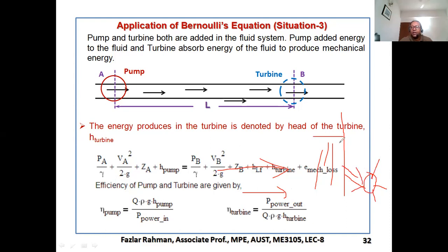Okay. Now this height, the potential height, is the fluid energy. Over here, velocity is 0. Then it gets out through a small opening with higher velocity, then it hits the blade and it is rotating. That means, what does it mean? It is taking energy from the fluid. So how can we write the equation in that case?